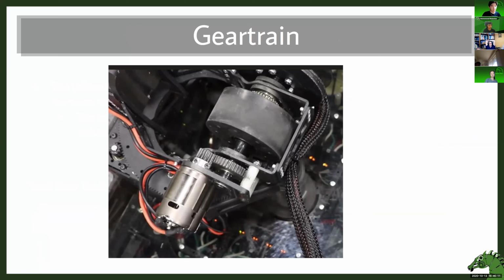All right, so this is an example of just very simple, just 2 gears. Right there is one of the standard motors you'll see in FRC. One of these things right here, that's a pro motor. And this is a small gear right here, and this is the driving gear. The driven gear is this large gear right here, and this is a shooter wheel. So you can think of that as one reduction system here, right? Maybe that's a ratio of, let's say, 3 to 1.